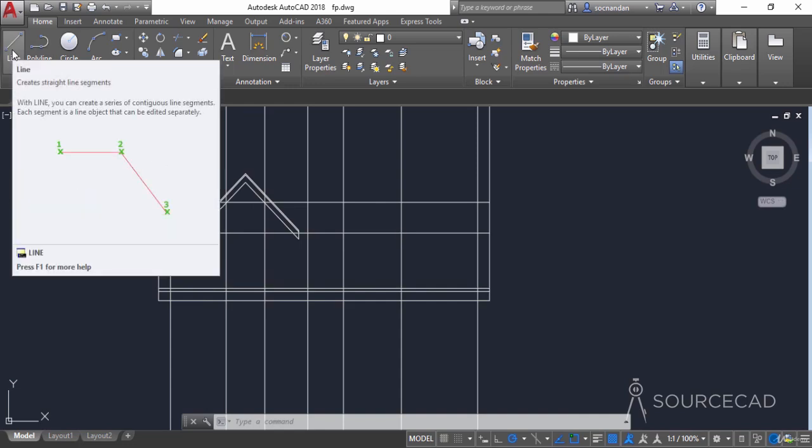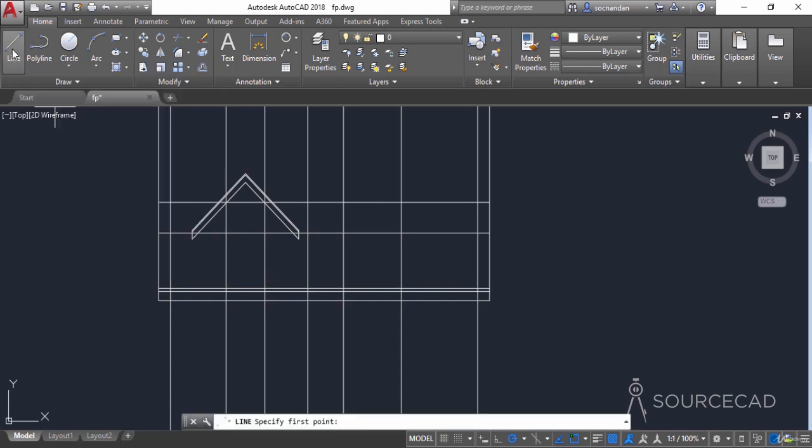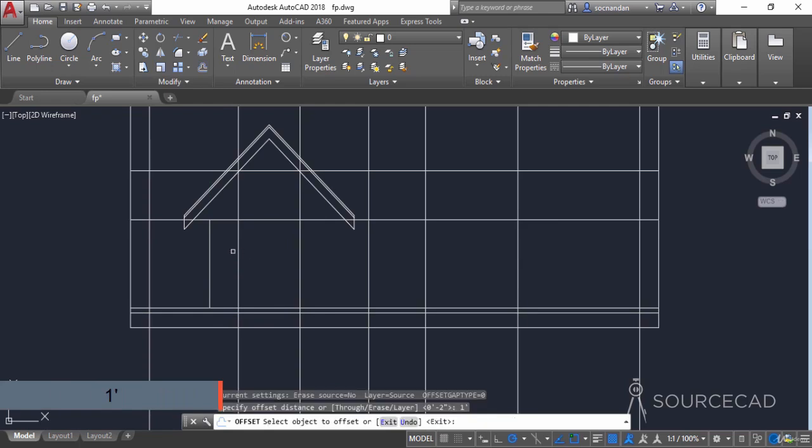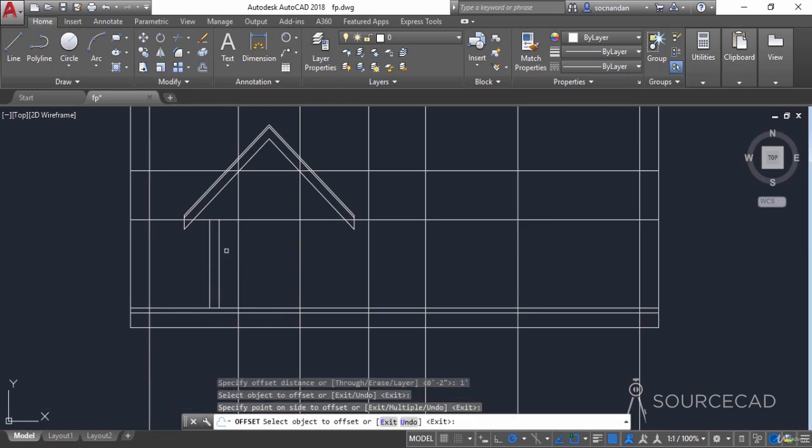And obviously, in this case, you may need to take the distance precisely, but now just to keep drawing simple, I'm using a random distance in this case. So I'll just select a distance from this point of any particular distance, maybe somewhere close to, let's say 3 feet. Okay, that seems appropriate. So I'll just click here and I'll just make it of this length. So I'll click here so that this line can be made, and then I'll go to offset and 1 foot as the offset distance. Click on this one and click here.